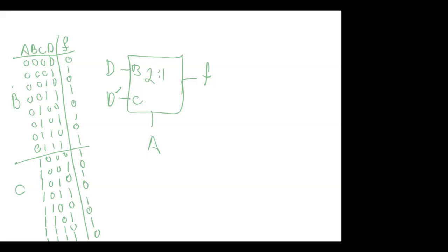We derived the truth table from our little, how you say, 2-to-1 multiplexer setup. Isn't that cool? So your 2-to-1 multiplexer has just implemented a 4-variable truth table, and you didn't need a K-map for that.